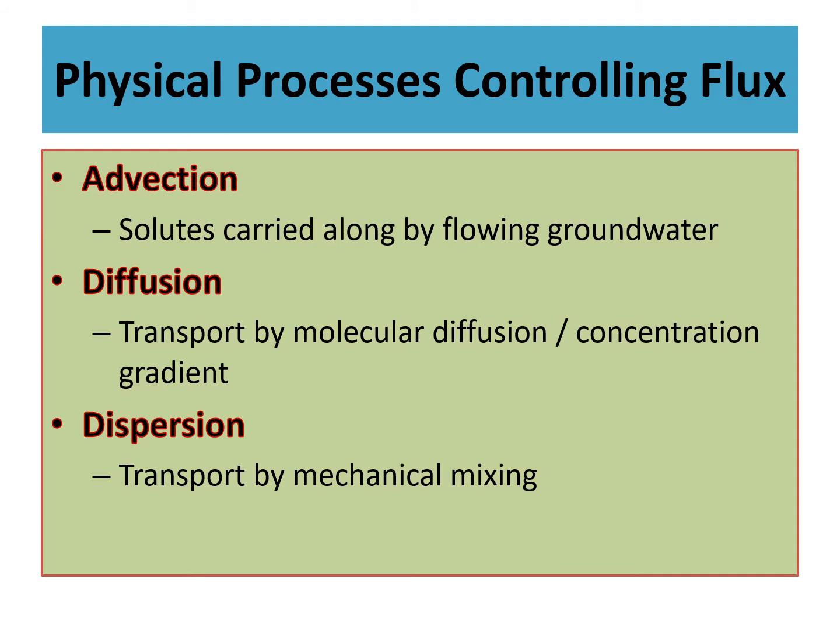Okay. So these are the physical processes that control flux, and if we talk about this, these are having three formations: advection, diffusion, and dispersion. So solutes carried along flowing groundwater will be expressed as advective movement, and it will be totally based on the groundwater flow. So being in the aqueous phase, the solute is supposed to move along with the water.